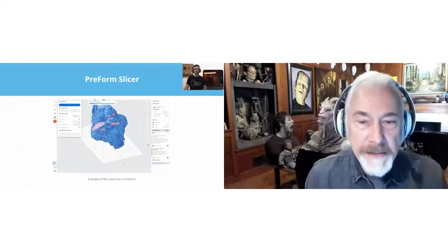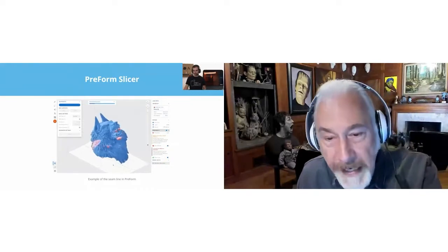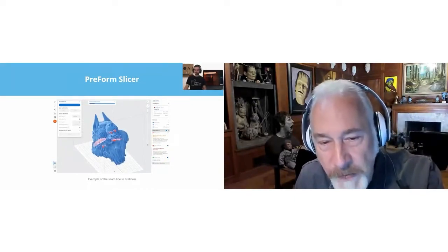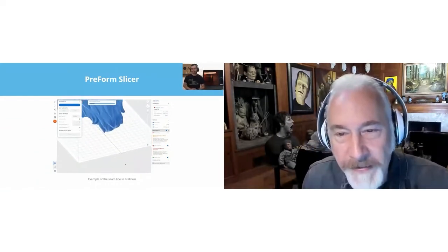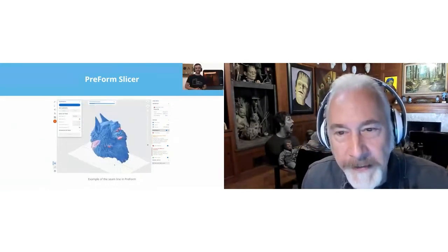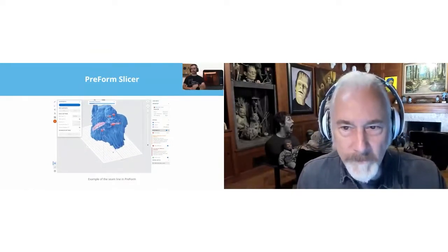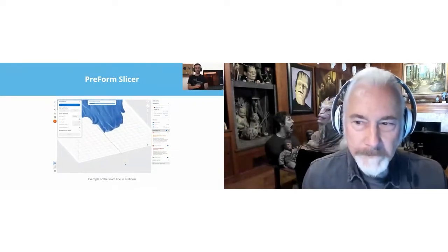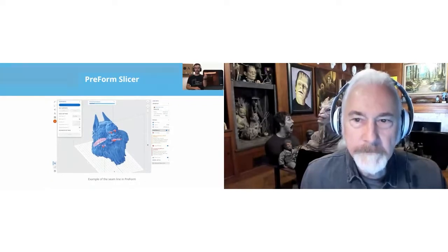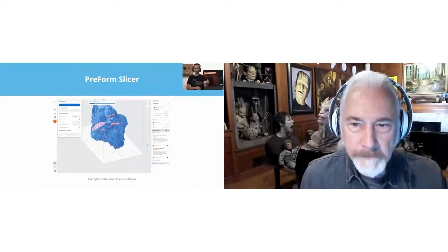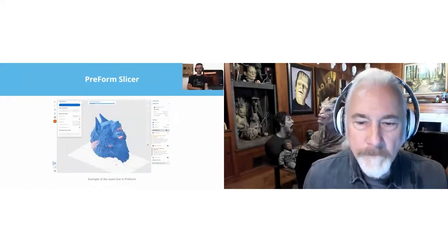But yeah, the slicing software tells you, like, I actually have a question about that. Go back to where you see the red spots in there. So that tells you it's got cups or whatever it says, where something might happen. Yeah. So this is before the support placements were put in place. That's what's really good too, especially if you are not sure what needs supporting. It'll highlight those spots and say, hey, you need supports here for this to be a successful print. And oftentimes you can do the auto-generated supports.